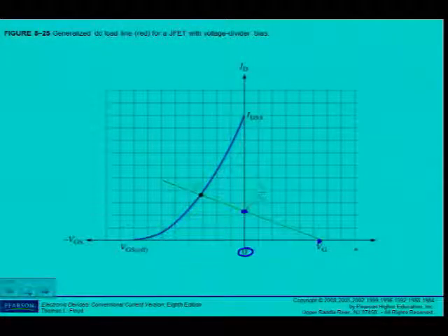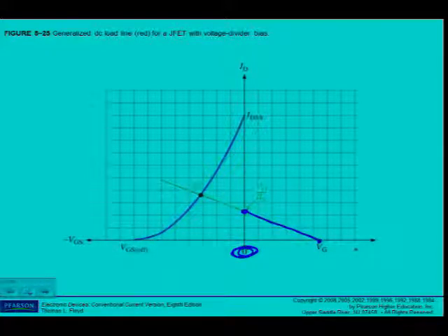There it is, the second point over there, where VGS is equal to 0, I calculated the value of ID. And now you can already see what happens. I draw my load line, connect these 2 points, but I extend the load line, that's why you have to have a ruler, until it cuts my curve, and you will write there, that's my Q point.